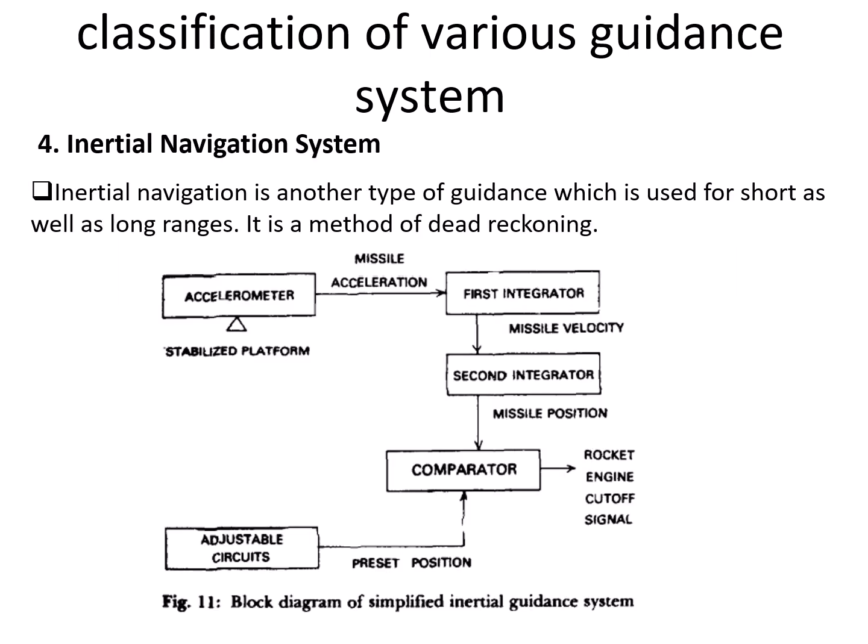Another is the inertial guidance systems. The inertial guidance system is a self-sufficient guidance system, where you are not relying on the outer world. All the equipment you require for the guidance system is carried by the missile itself. It is similar to the inertial navigation system, but it is not using the navigation component. Here we are using the accelerometer and the gyroscope to find out the range and bearing of the missile, and from that we are able to keep tracking the target and keep our missile in the line of sight of the target. The advantage is that it is not transmitting any electromagnetic signal, so it cannot be jammed, and it can fly in any weather.